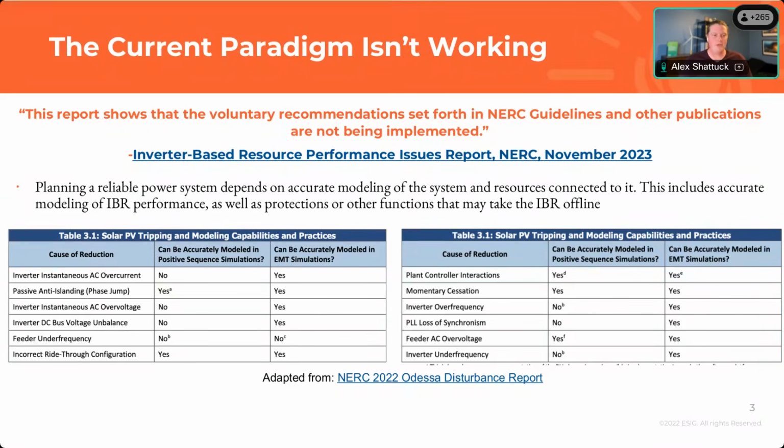So if we keep to the current paradigm and only do phasor domain, we're going to miss a lot of things. If we move on to EMT only, we will catch a lot of things, but there are also significant other considerations for EMT only, like knowledge of the stakeholders, computers, and simulation times. So what that means is we need some sort of combination of both, which I'll get into a little bit later, how that could work.